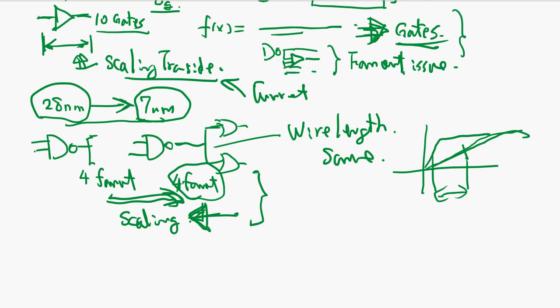And who does that? Usually a chip company making its own chips has engineers internally who qualify those library parameters. They make a lot of test chips and find out what fanout and delay time can actually be achieved.